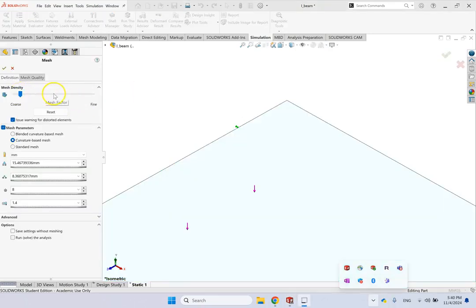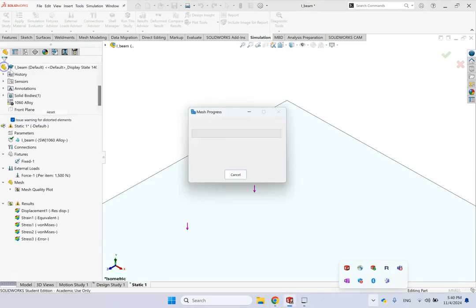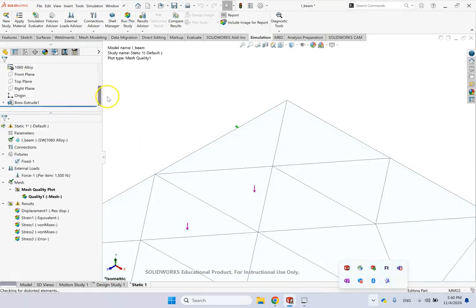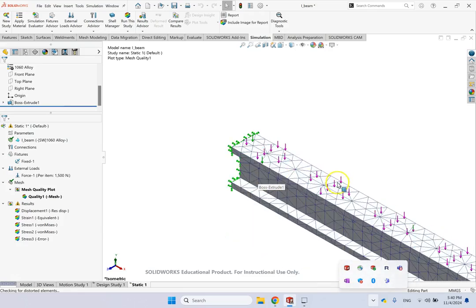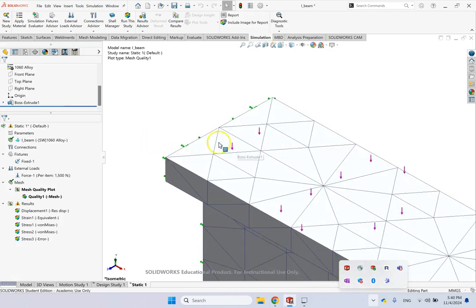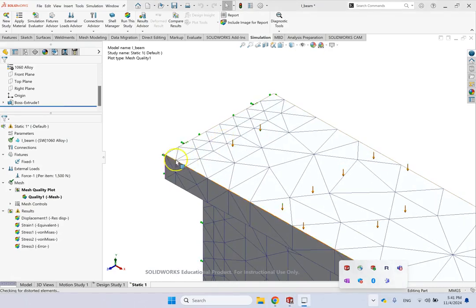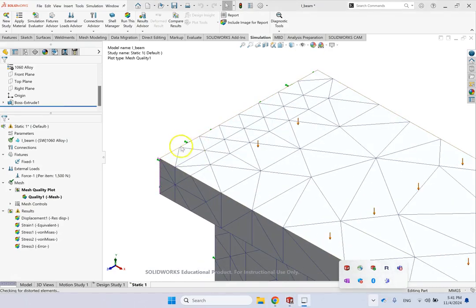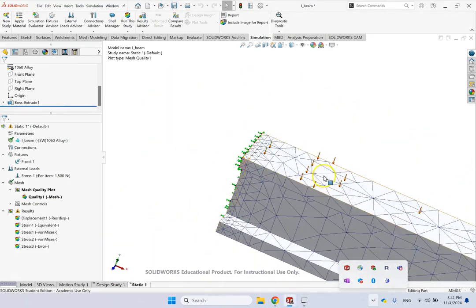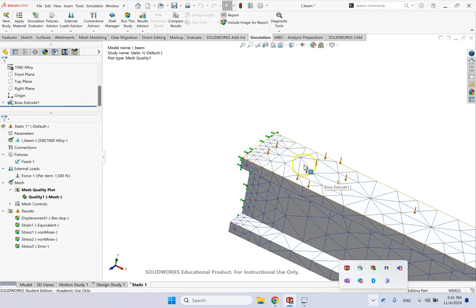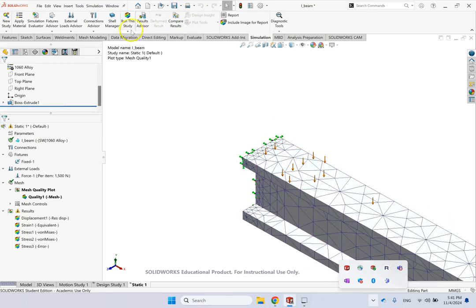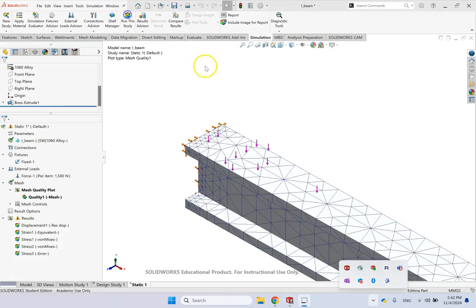So here I bring this from the middle to the coarse side and make it a very coarse mesh. Let's first look at it. You see, now it's not even locally controlled, although I can locally control that a little bit over there. Let's just apply a local control here. So now I have smaller mesh elements close to that surface, and then bigger elements elsewhere. And you see the total elements are much, much bigger than last time. So if I go ahead and run this, let's see what you get.